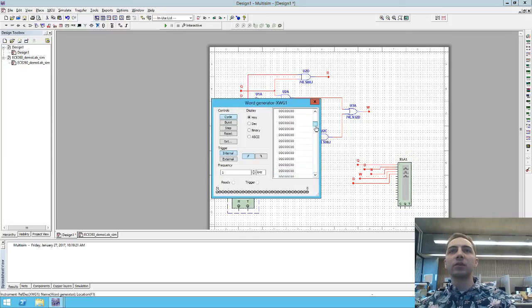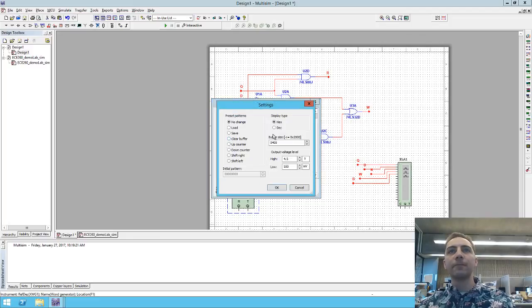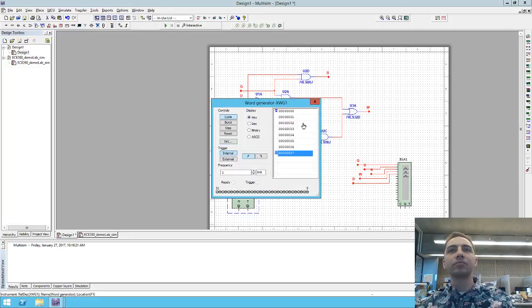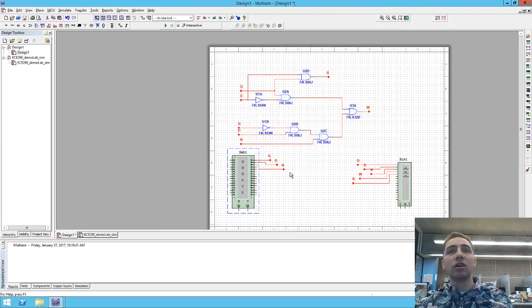By default, it will generate something like 4096 or something steps. We're going to change that to generate just 8 steps. That's the size of the buffer. And we're going to automatically create an up counter. And that's it. That's all we have to do to trigger this and set it up. We're going to generate a change 1,000 times a second at a frequency of 1 kilohertz.